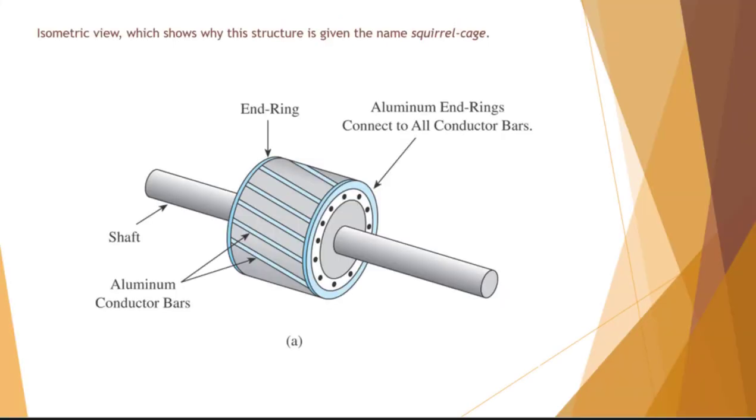This is the rotor out of an AC motor. It's called a squirrel cage motor, and you kind of see that it looks more like a wheel to me, and here's the shaft. You see there's no brushes. There's no brushes in an AC motor. And brushes wear out and cause heat and sparking. So brushes in motors can be a problem. If you ever had a power drill or a tool that you had to replace the brushes, or a starter in your car, if they wear out, you're kind of dead in the water.